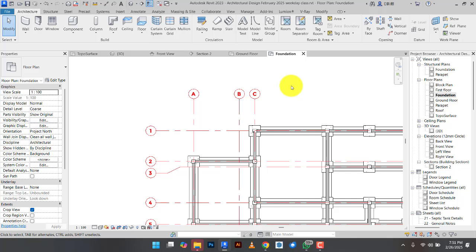That's how it works. So sometimes someone will give you a work and when you open it, you want to put grid. When you put a grid, maybe you see three. It starts from three. Maybe the person tried placing grid two times. So just change it to one. Then when you continue, it gives you two, three, four, five, six.